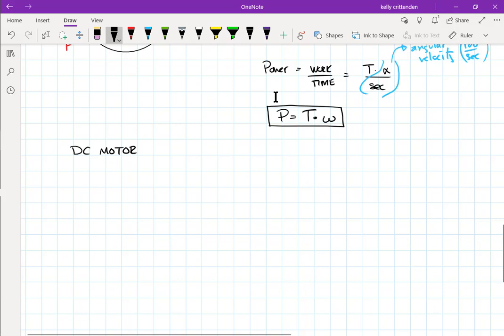This little guy was spinning, most of them were around 10,000 RPM, so super fast, but their torque output was rated in the range of, not exactly, but let's make it an easier number, 1 ounce-inch, so not inch-pound, inch-ounce. Inch-pound wise, I didn't calculate that, let's see. Basically 1 divided by 16, not 10 divided by 16, 1 divided by 16,